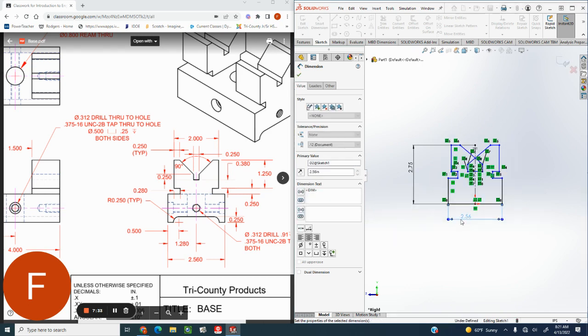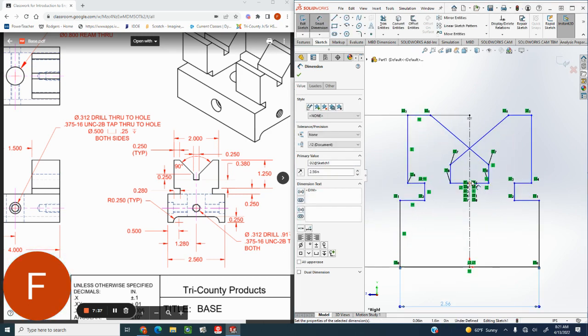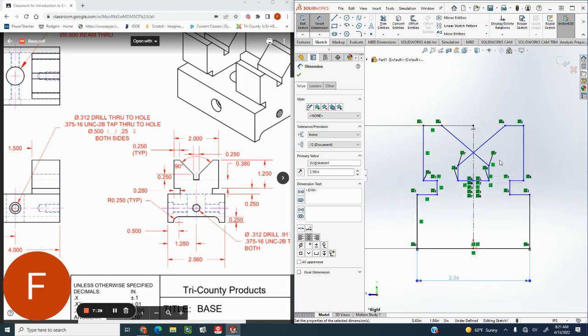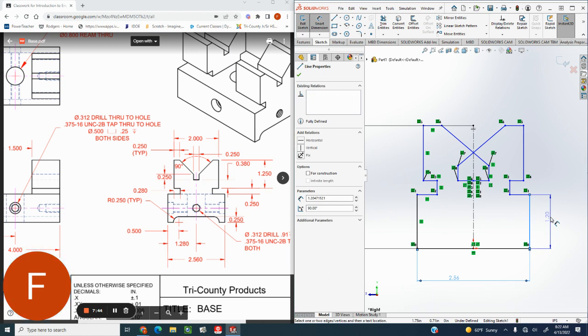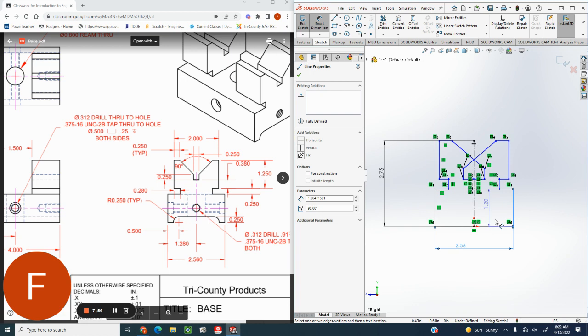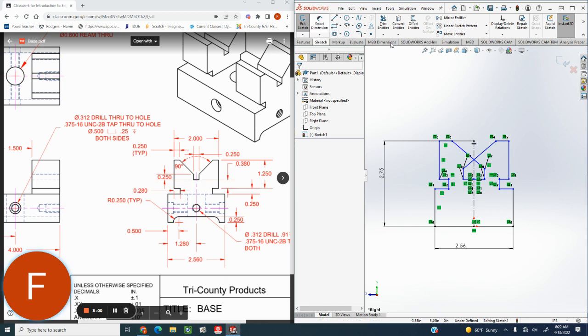See how messed up this becomes here? A little bit. See how I inverted these? I'll fix that in just a second. Let's go ahead and get this. Again, that dimension wasn't given. We have to calculate that. It is 1.5 here, and we have 2.75, so that equals 1.25. But for the sake of doing things properly, we should probably do it the way it's dimensioned. So let's go ahead and do this.